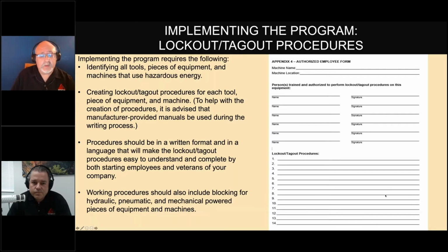And I agree with you, Sam. This is very important. Also, what should be included in these procedures is you should write anything that could be other than just more likely electricity. We're talking about blocking a certain part of the machine or parts of the machine that could be maybe mechanical, right? Or it could be pneumatic, or maybe it'd be multiple energy sources. So they have to be listed down as well, because most people think it's just electrical, and that could be a problem.